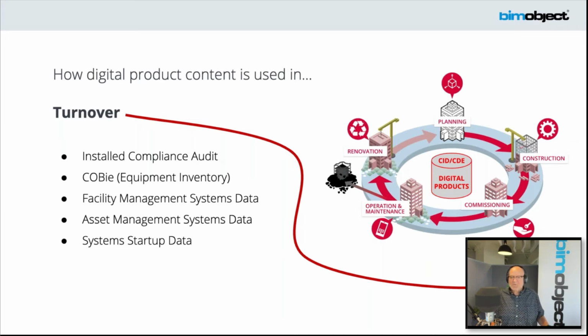This is all readily available through that, and this is an area that we haven't seen a lot actually implemented yet, but all of this data at commissioning for all this equipment is an amazing foundation, and in discussions I've had with a lot of facility owners, for IoT monitoring, like pressure differentials in an HVAC system to understand when to replace the filter versus kind of monotonously changing it out every 30 days or 3 months, whatever it's called for.